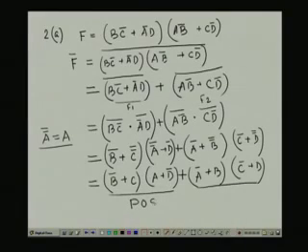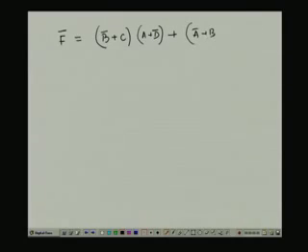This is one POS, this is also one POS, but this one plus exists here. So this is not any standard form. So if I want to make this a standard form, then we have to simplify it further. So F complement becomes (B bar plus C)(A plus D bar) plus (A bar plus B)(C bar plus D).